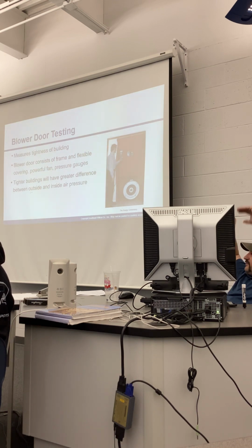We'll take the trim off of it, insulate around it, figure out, is it a poor efficient window or is it installed incorrectly? What's the problem? Another thing that might be an issue is seals around doors, holes around the furnace going into the attic, or into the crawl space, floor vents that have big gaps around them. So you just go around and you find what the problems are and you seal them.